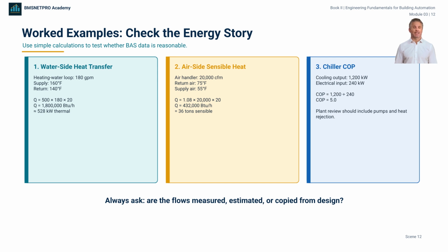They are quality checks. Always ask, are the flows actually measured? Are they estimated? Were they copied from design? Are the sensors calibrated? Are the units correct? The calculation is only as trustworthy as the evidence behind it.